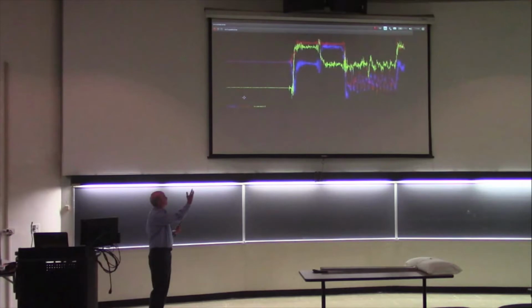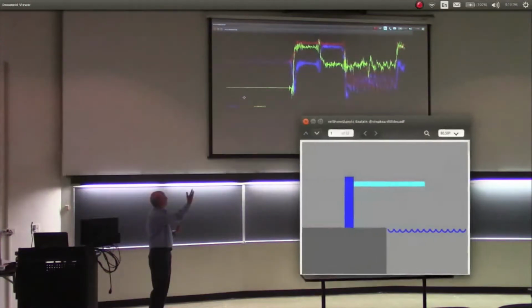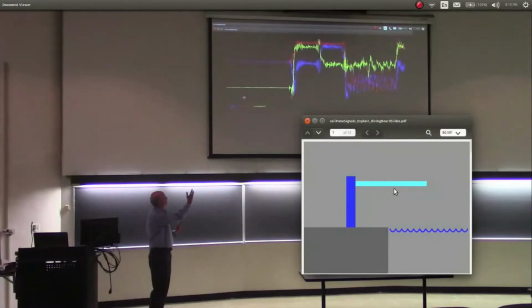First, how do these accelerometers in phones and Fitbits work? I'd like to use a diving board analogy. Here we have a diving board with no mass on the end of it. It is neither pushed up nor pulled down. When I place a mass at the end of the board, it bends. A similar process is taking place in the accelerometer of a phone when the board feels the effect of gravity. In the sensor, the board is made of a piezoelectric material that creates a voltage in proportion to the strain on the board. Of course, the sensor is minuscule compared to a real diving board.